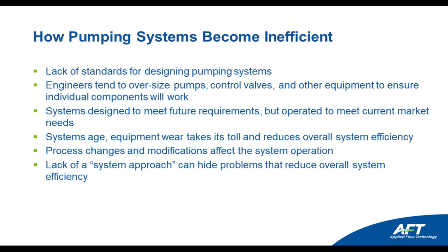How can pumping systems become inefficient? There are several ways. One is having a lack of standards for designing pumping systems. What we have found is that doing a hydraulic flow analysis is kind of a luxury, because codes and standards typically do not require the piping system to be analyzed, if at all. So if the engineering company is not asked by the operators to do a flow analysis, they have the choice to even completely ignore doing one, which is not recommended practice, but it happens.